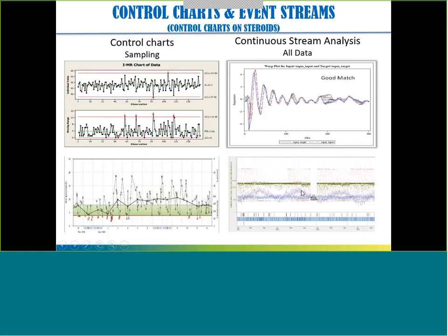Sensors have what are called tags, and the tags give you the measurements, and you can see random noise and a signal. The signal to noise is like a control chart, and it gives you information. What I call this is control charts on steroids. You can still use the Western Electric rules, even though this data is coming through very rapidly. It's like an individual range chart on steroids, and you can do the moving range also.